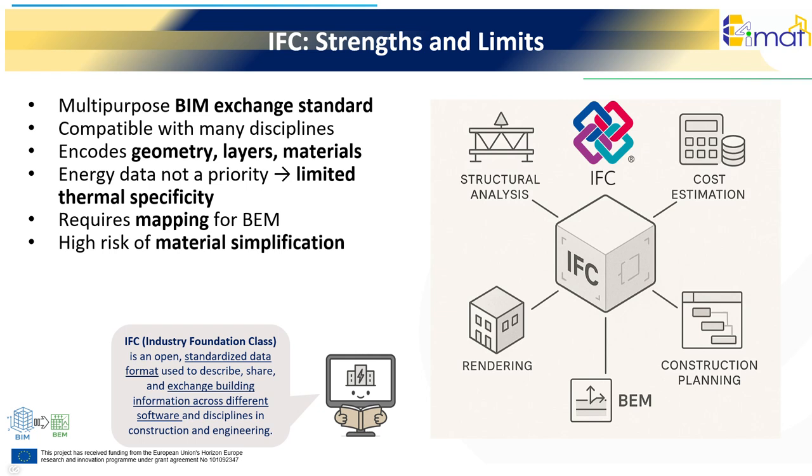IFC was not designed as a specialized thermal or simulation schema. Its material and construction entities exist, but their level of thermal specificity is intentionally limited, because IFC must remain compatible with a wide range of applications that do not require detailed energy data. As a result, when a BEM tool reads an IFC file, it must perform a mapping process, translating IFC materials, layer sets and properties into the structures required by the simulation engine.